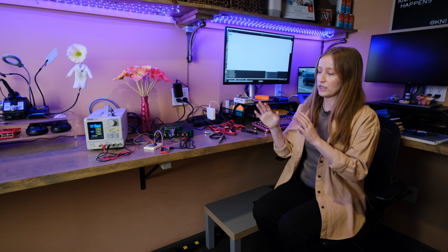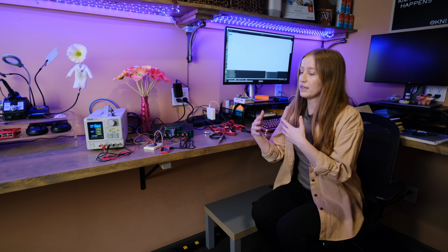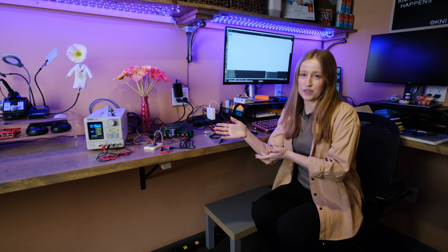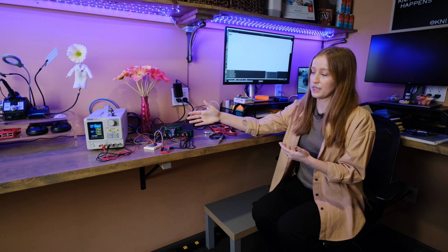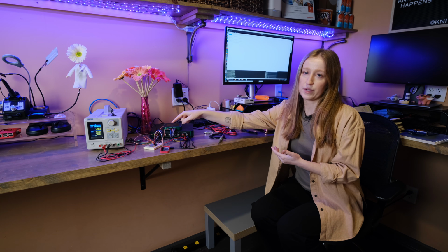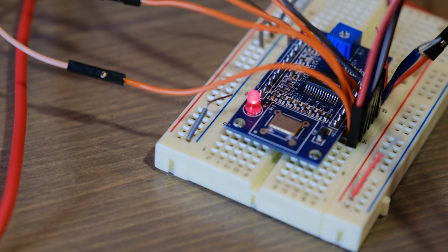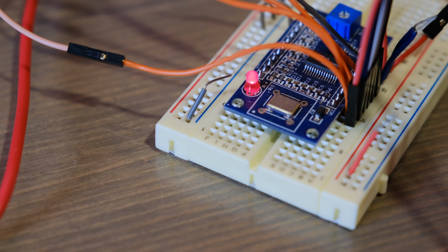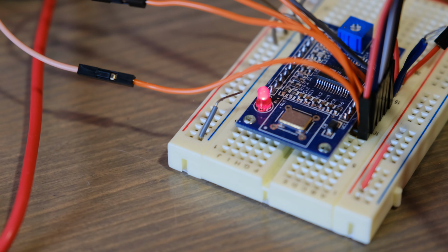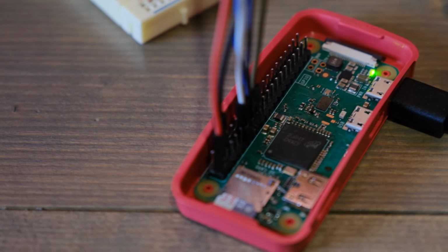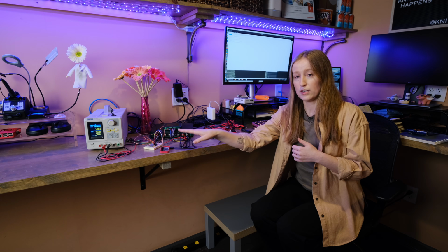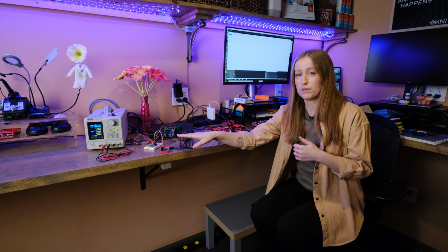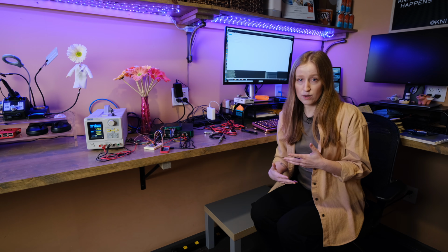So, going over my particular setup, some of you might recognize this test setup from a previous project post. This is my test setup for my little direct digital synthesis chip. This little blue board here is a development board for the AD9850. I have a Raspberry Pi Zero running a Python script that provides the digital interface to the AD9850 chip that tells it which frequency to output.